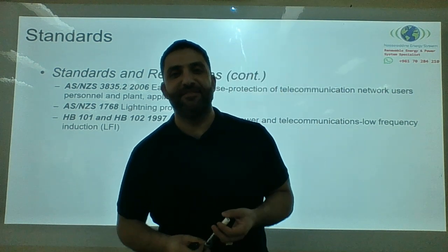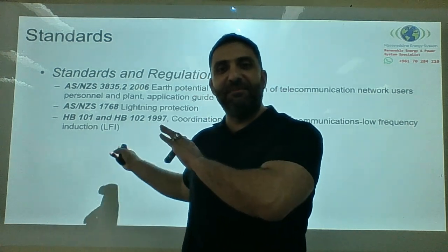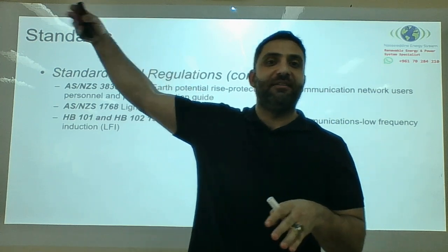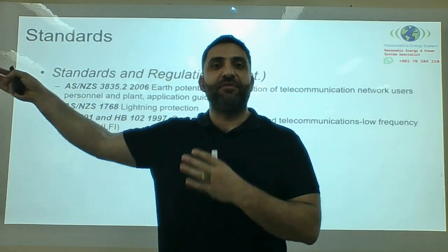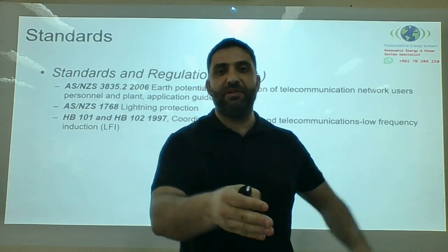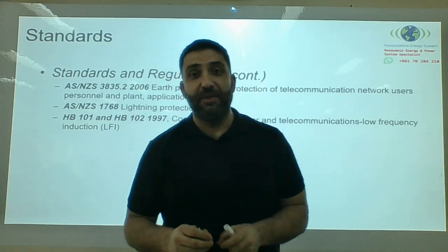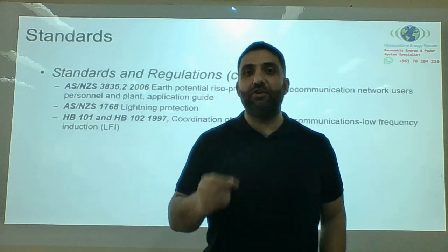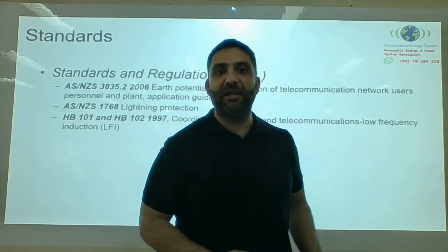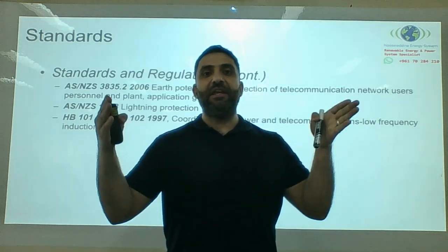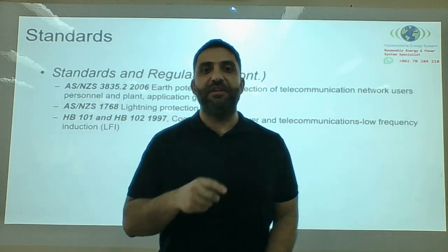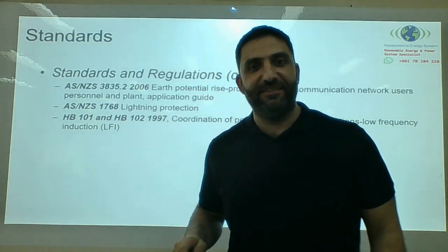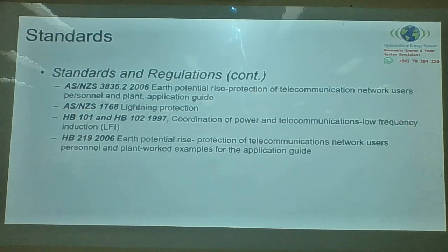AC interference. So let me explain a bit about the AC interference. If you have a transmission line running 50, 100 meters away from you, could be 200, depending on the length of the parallel path, and you have a fence or a telecommunication wire using copper or pilot wire for communication, if they're running in parallel for a certain distance, there is an induced voltage due to AC interference, LFI. The earthing system is very important.